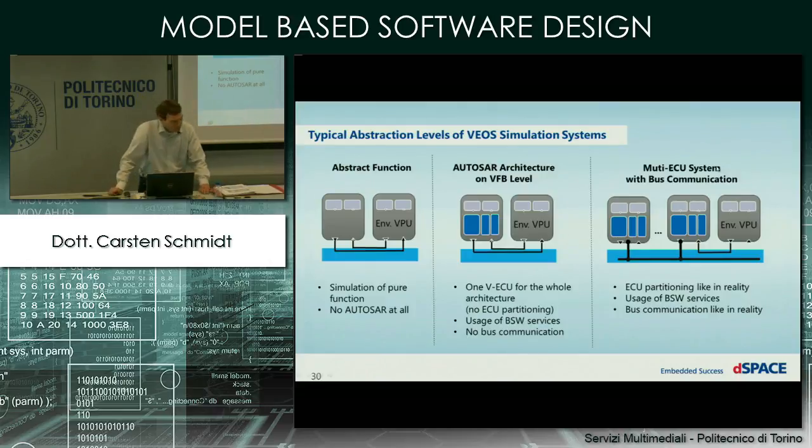Okay, so as you can see here, whenever the detail level is quite deep, you have AutoSAR involved. So AutoSAR is a kind of enabling technology, because if, for example, these interfaces here are not defined, you basically don't have a chance to provide a generic tool that supports this creation of the virtual ECU.